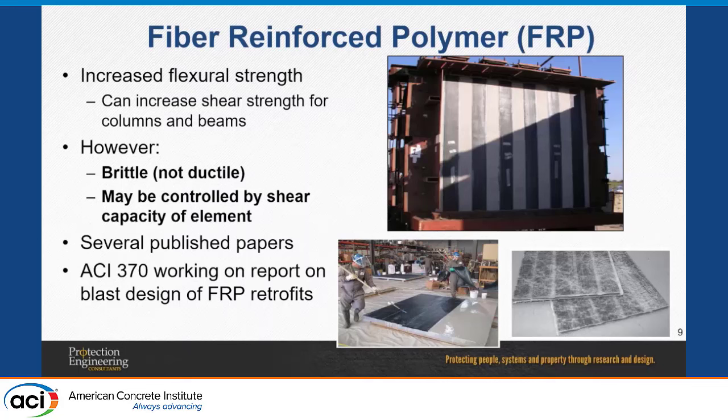Once you reach that ultimate flexural capacity, depending on the response limit that you're looking at, you'll see that response limits won't typically go beyond a ductility ratio of 1.5 or something like that. So that's one thing to keep in mind. And the other one that I mentioned earlier, and I will keep mentioning because it's common for all the retrofits, which is the shear. Again, this increases your flexural capacity, but you're not increasing your shear capacity with this, unless it's a beam or a column, where you can do that.